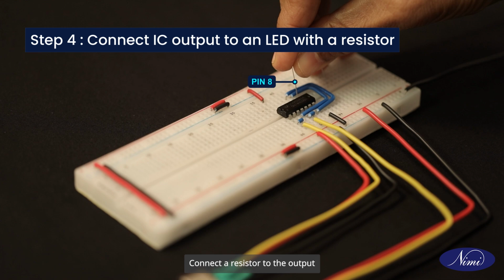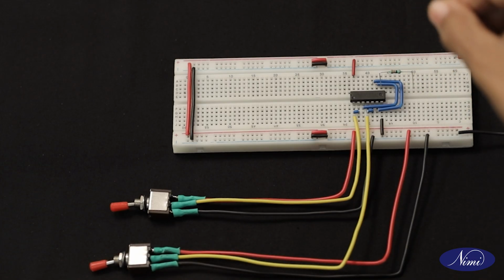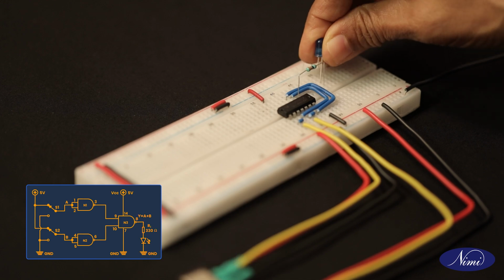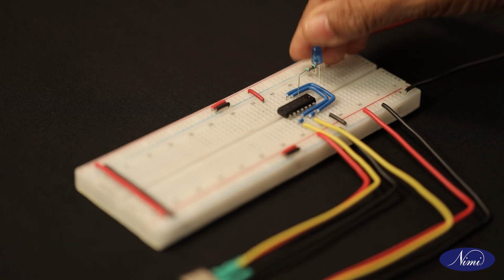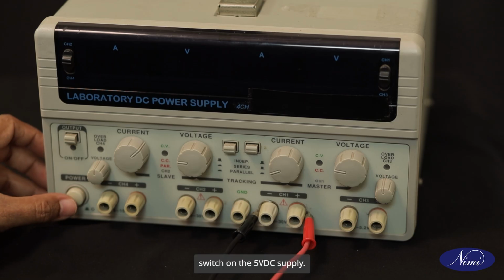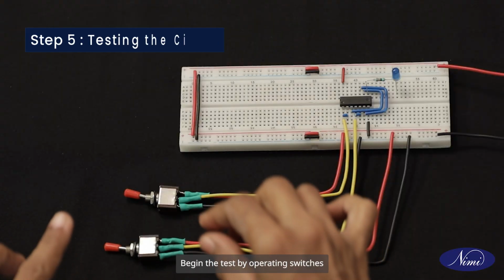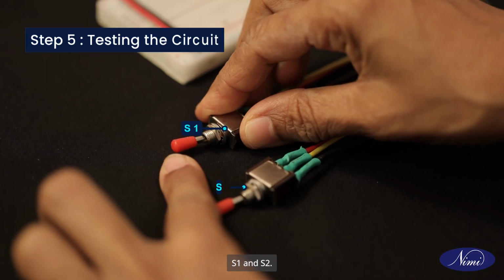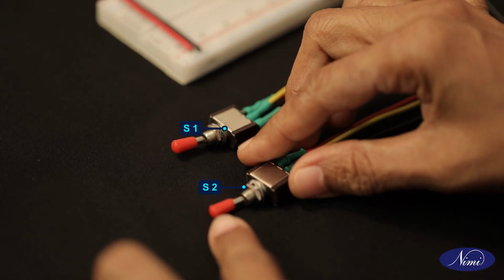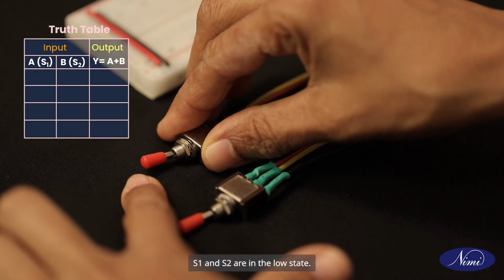Connect a resistor to the output pin number 8 of the IC. Attach the LED as well. With everything checked, switch on the 5V DC supply. Begin the test by operating switches S1 and S2. Check if the toggle switches S1 and S2 are in the low state.